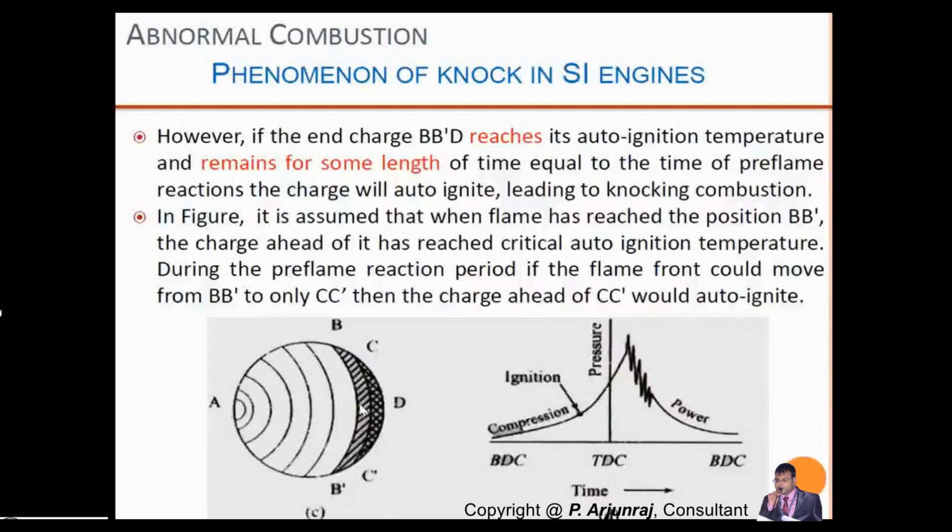If the auto ignition is going to happen at this point in time, you get the other flame in the opposite direction where the distance is going to be lesser. So the intensity of noise is going to be lesser. But assume that the flame is moving from the mid position, or 50%, from A to D and D to A. Then the velocity at which both strike is going to be higher. You get a high level of sound.